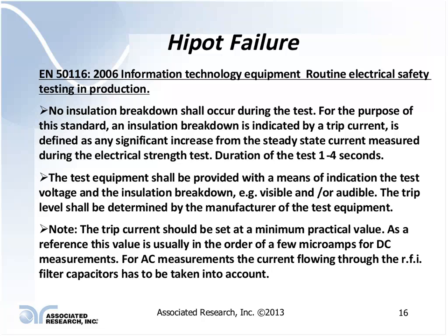So the meter will never stabilize on a reading before the test is over with. So how do you know that you're actually applying the correct potential? One way of doing that is to make sure that you do have a tester that is regulated as far as the output voltage potential, or have something that is a brute force tester that has a large current capacity.